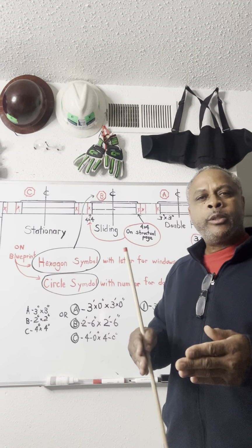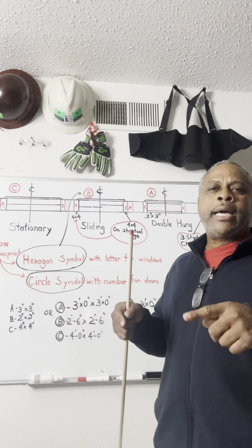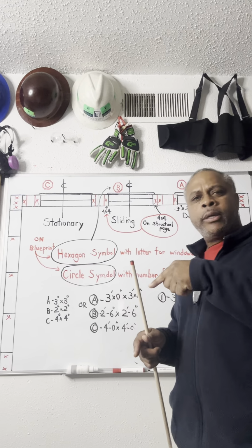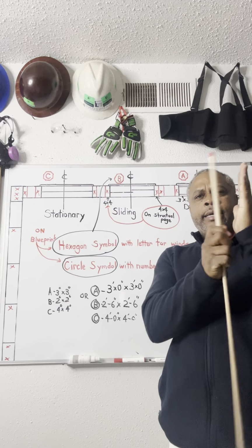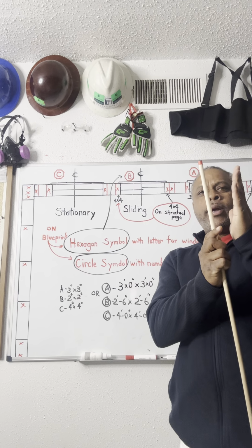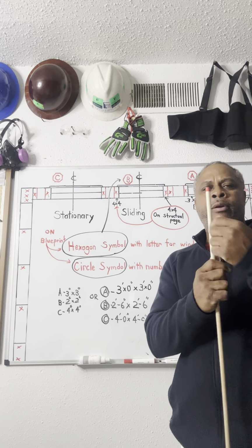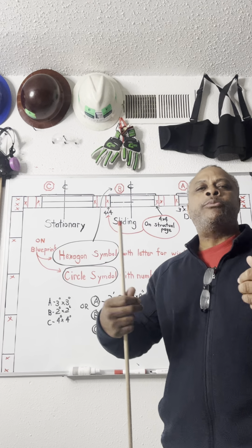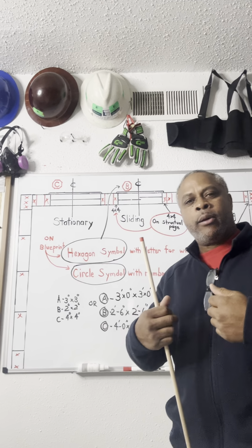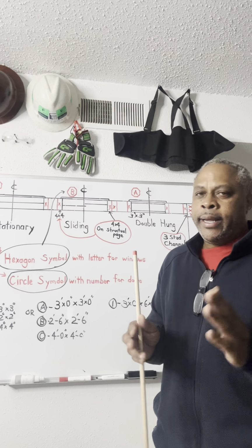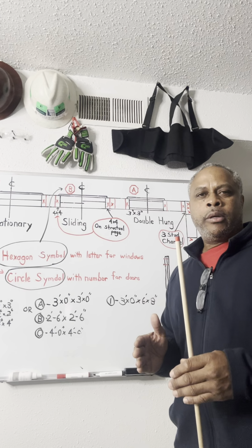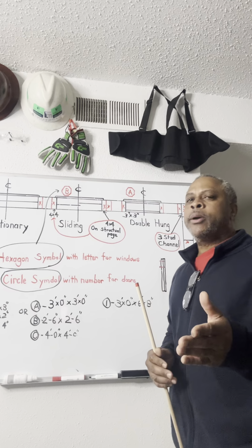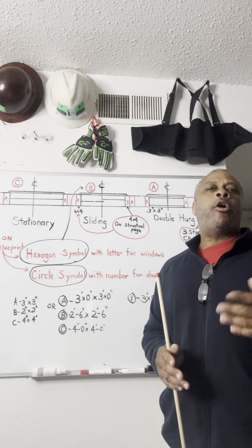If he has to shim or pull a trimmer out, he can do a California tie with a nail bent over with another nail, tying the king stud to the trimmer. If that trimmer has to move that way, he can nail these two members together, even with the gap there. This is the rough framing stage. The shims go in between the trimmer and the jamb. Always plumb your hinge side on any doorway. That side needs to be perfect. The other trimmer on the other side, you can play with it. We call that a floating trimmer.